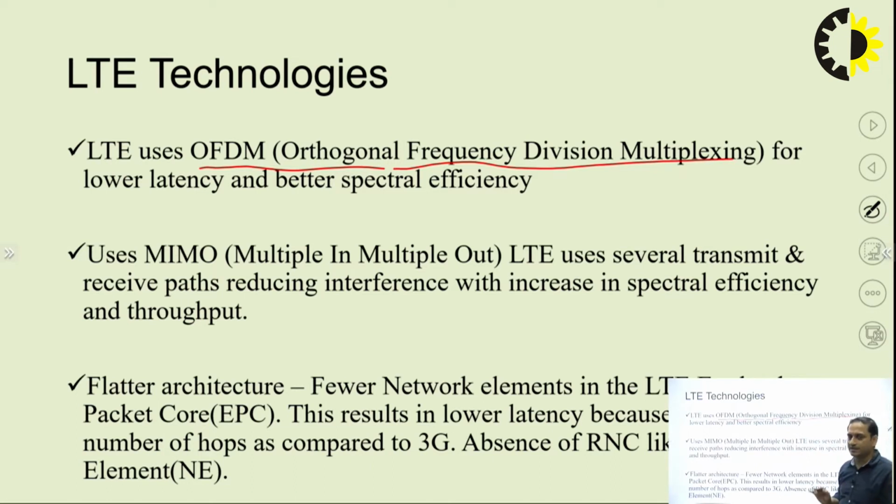In this method, they have divided the complete bandwidth of the signal into chunks of bandwidth. High data rate signals can be converted into low data rate signals, and then we modulate those signals with different subcarriers. This is the feature of the OFDM system, and after that we combine all the signals and transmit them.